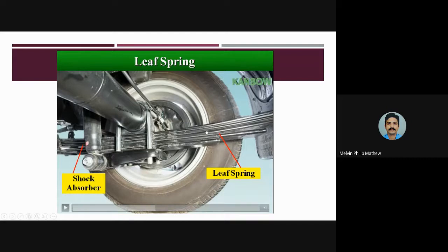You will ask how, if the suspension acts, the plate will not break. The material is made of a special material so as not to break under the various loads occurring inside the suspension. But still the suspension action is lower, and for that purpose these are becoming obsolete. It is only present at the rear wheels in trucks, but in the front there is usage of coil spring suspension itself.